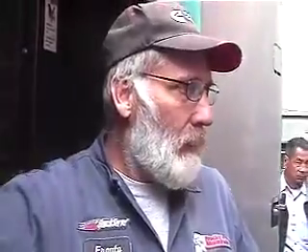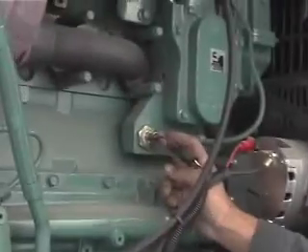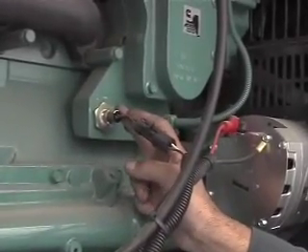You have 2 shutoff valves on your block heater. There's one on the upper side, there's one on the lower side. If you shut those 2 off, you need to be turning off the block heater. If you don't, it's going to sit there and cook, and you're going to end up burning out your block heater. You have 2 thermostats for the block heater. This thermostat right here is the actual thermostat that turns the block heater off and on.